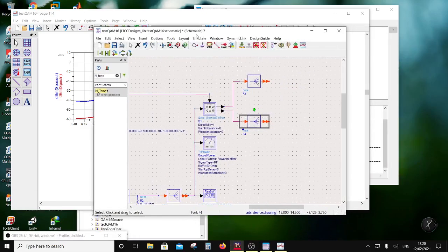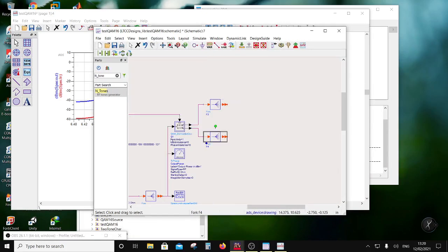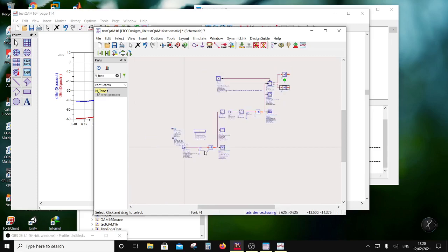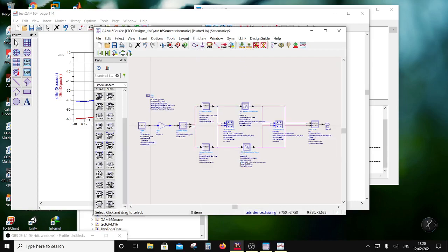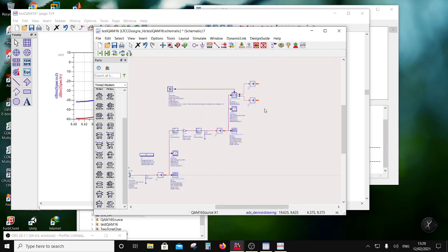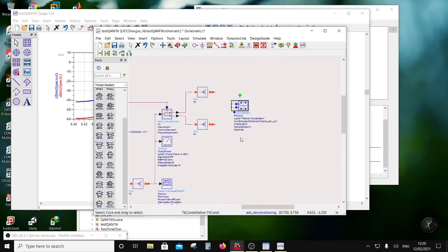Okay, so now here what I'm going to do is put back the constellation, which will be the demodulated constellation. So I am going to go in here and copy that. So TK plot, I'll copy this one, Control C, and come up and then say Control V. Okay, so now in this case it's going to be demodulated constellation. So I will call this demodulated constellation.